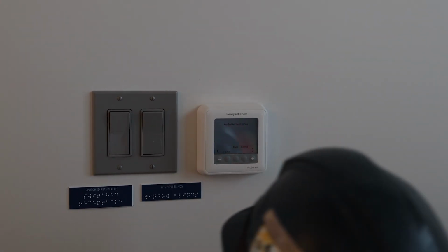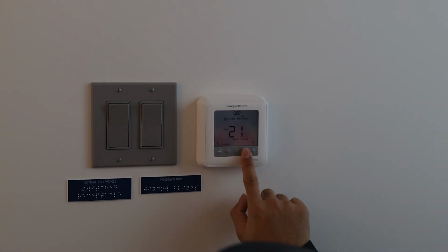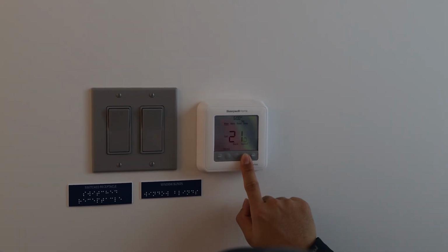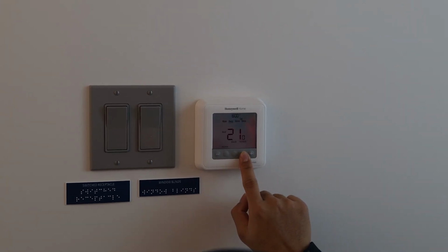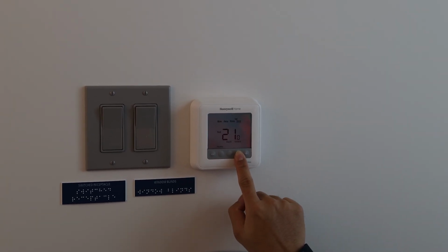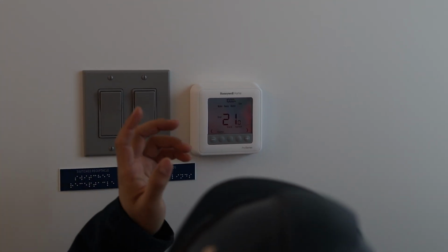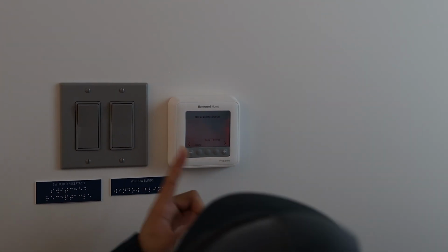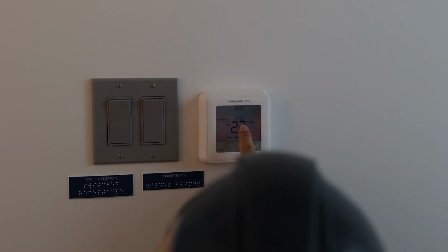And then the next one is the weekend. Saturday, same thing. What time we wake up, and the set point for heating and cooling. What time we come back home, what time we leave home. That's how we program the schedule. There are 4 modes: wake, away, home, and sleep. So that's for the schedule. After changing that, it will say save.